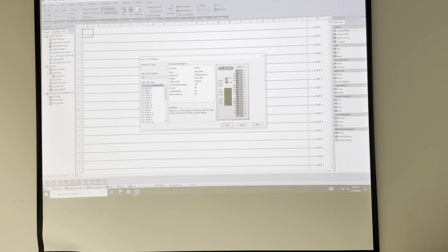Click OK. And look at this. This is the terminal block. X are the input. Y are the output. On X, I connect my switches: thermostat, motion sensor, limit switch, pressure switch, and at the bottom, the output. It could be electrically feeding a contactor coil, but the output is 24 volt DC.